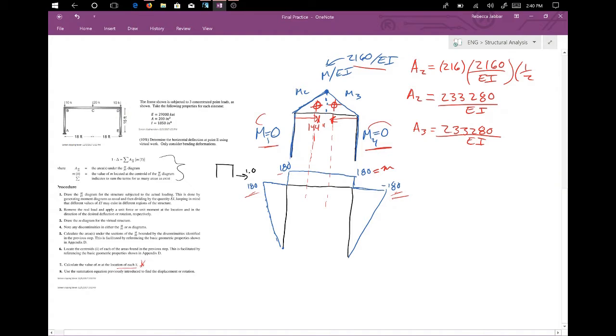So again, take the location of where these centroids are on this top part, trace it all the way down here, and see what these values are for little m, not where their centroids are, which, if it were in half, its centroid would be over here. That's not to confuse you, but take the centroid location on the real moment diagram and see what value of little m it gives you.